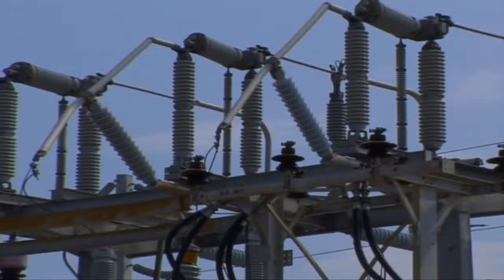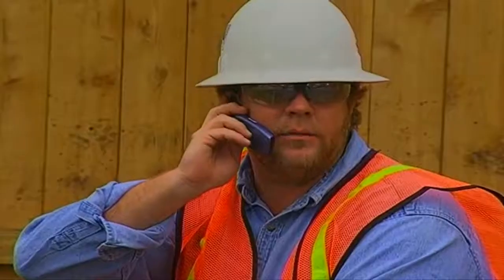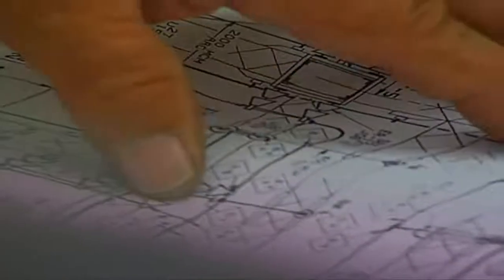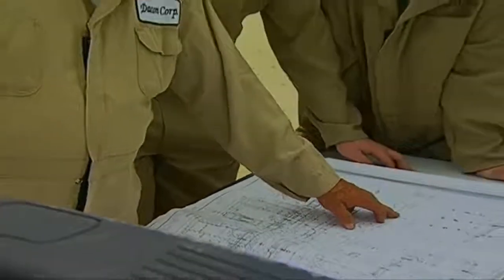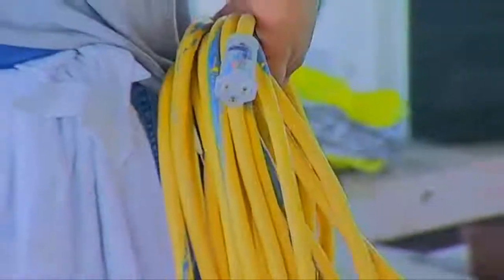Voltages over 50 kilovolt require distances greater than 10 feet. Scaffolds can only be closer to overhead power lines if such proximity is necessary for the type of work being performed and if the power company or electrical system operator has been notified and has either de-energized the lines, relocated the lines, or installed protective coverings over the lines to prevent accidental contact with the lines.